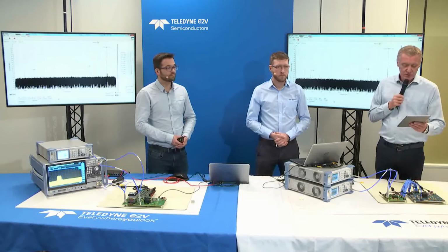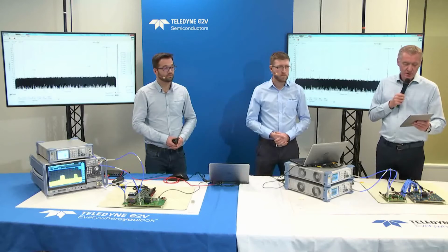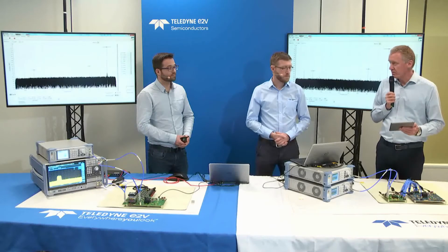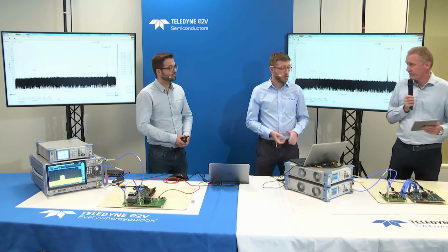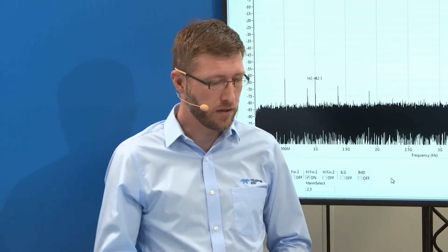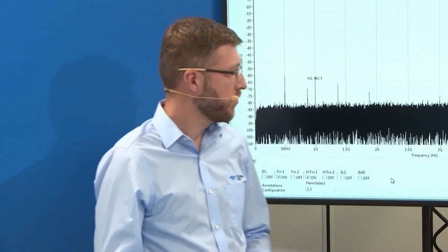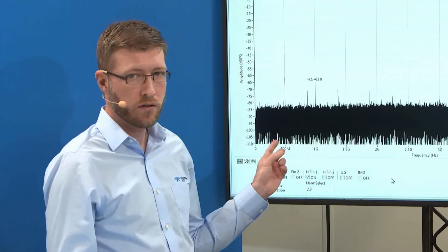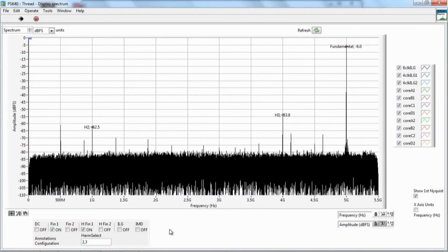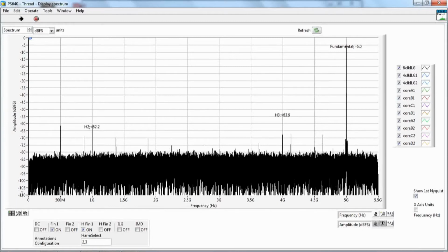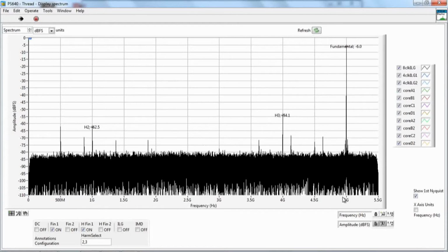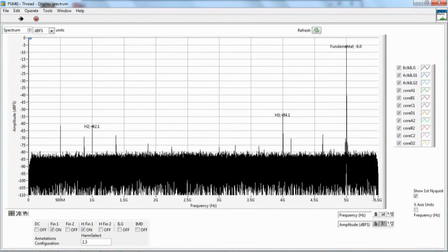We have the second question. The other question from Eutelsat is, what would be the maximum instantaneous bandwidth in Ka-band? Concerning this, for the EV12PS640, here you can see the maximum behind us. You can see the maximum instantaneous bandwidth with a clock input at 11 gigahertz, basically the corresponding Nyquist zone, extending from close to DC to 5.5 gigahertz.